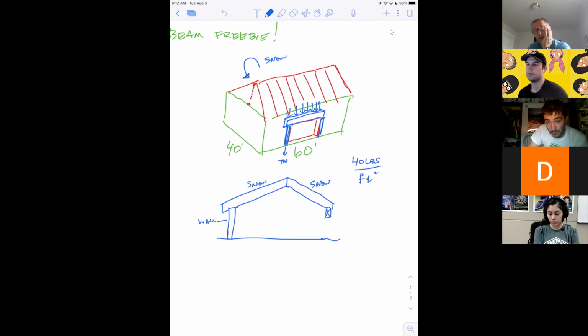So I had to look it up on a website, and up there it was like 100 pounds per square foot. So you actually have to know where it is. I'm in Idaho right now and it snows more here. I would look it up. It would not be 40 pounds per square foot, even though I'm just in a residential neighborhood right now. So you got to know what that weight actually is. But anyway, for where you live, it's 40 pounds per square foot.